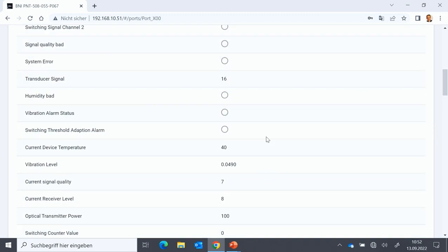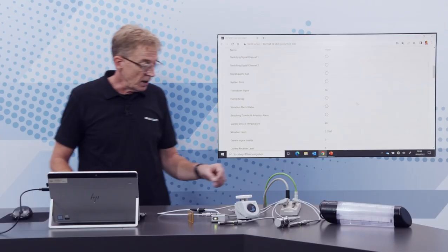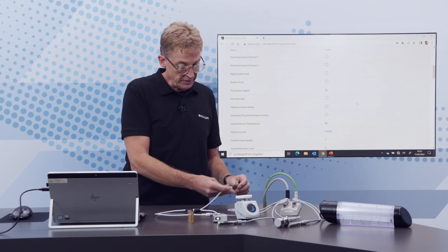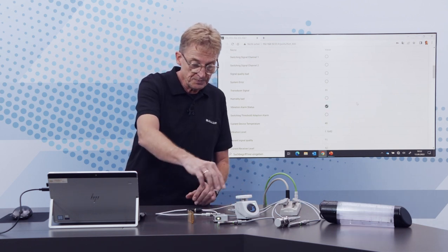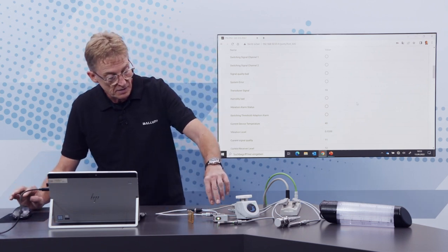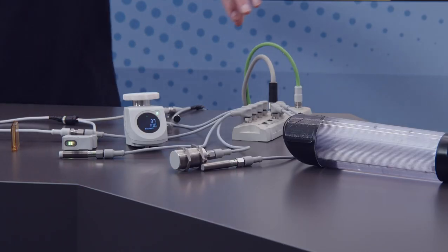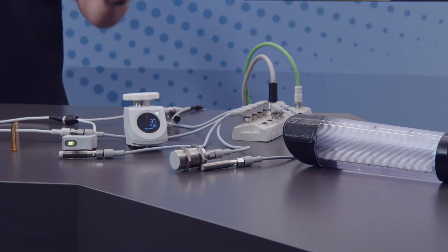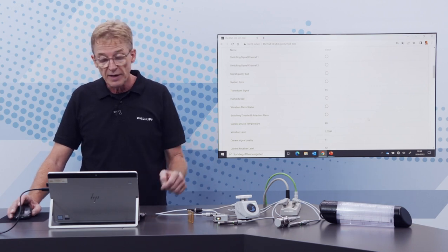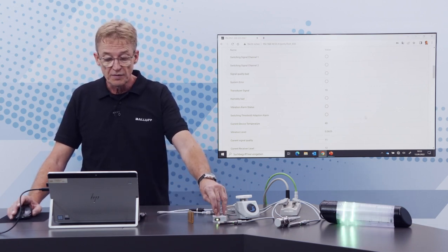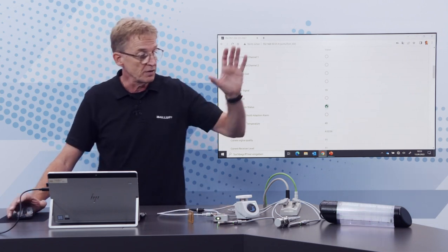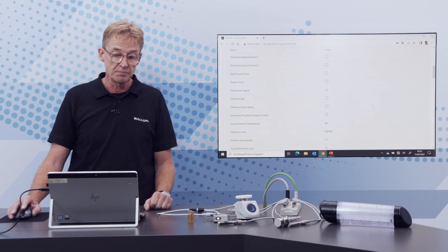And let's go back to the process data, and now I want to connect this standard device here directly with pin number 2 of our device. And now I just took the pin 2 of this device and transported this directly to this standard digital signal light. So whenever I create this vibration now, you see that not only the alarm status is set, but it's also transported directly to the signal light.